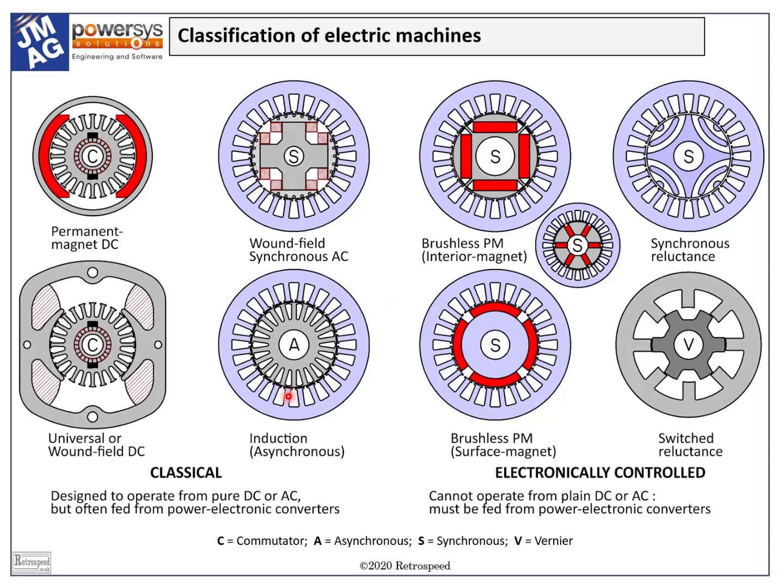The flux rotates while the currents and voltages follow more or less sinusoidal waveforms in time. Also, in the AC machines we have to control 3 currents instead of 1, and in the case of the wound field synchronous motor, the field current as well.